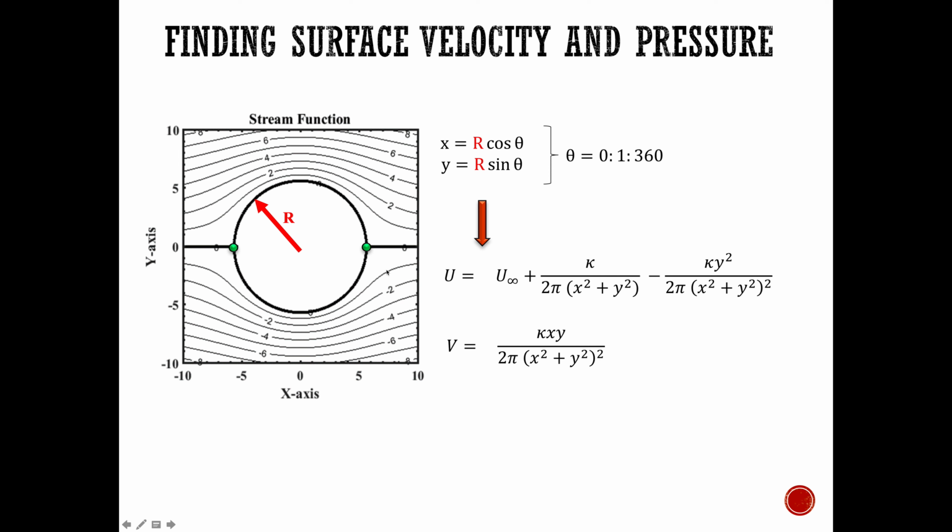All right, so as you can see, the flow over the cylinder kind of resembles Stokes flow, where the flow going over the object starts at a stagnation point, then the flow goes around it, and then there's a stagnation point in the back, and then it goes straight. If you consider the symmetry of the flow about a certain axis, we can see that the flow is symmetric about the y-axis, and the flow is symmetric about the x-axis. So the flow is symmetric and the velocity is symmetric. If the velocity is symmetric, the pressure is symmetric. So all this shows that the cylinder has no drag, which is sort of not what